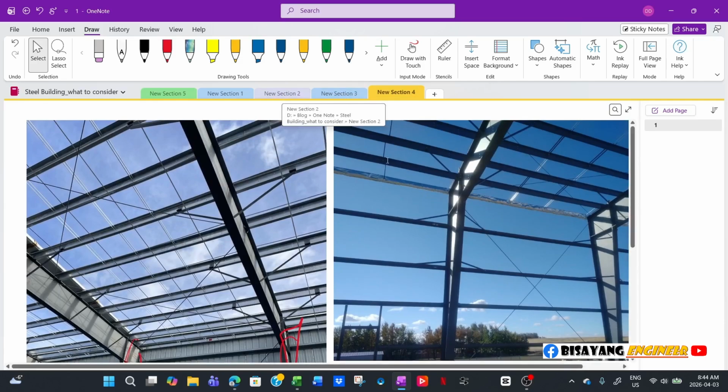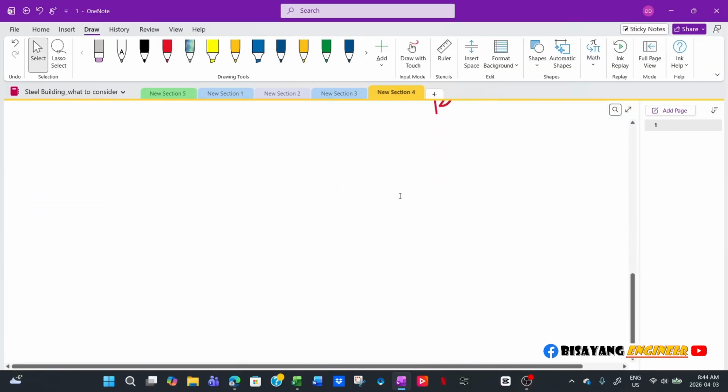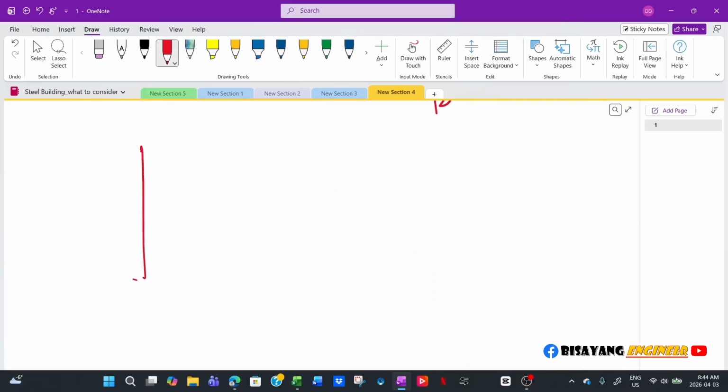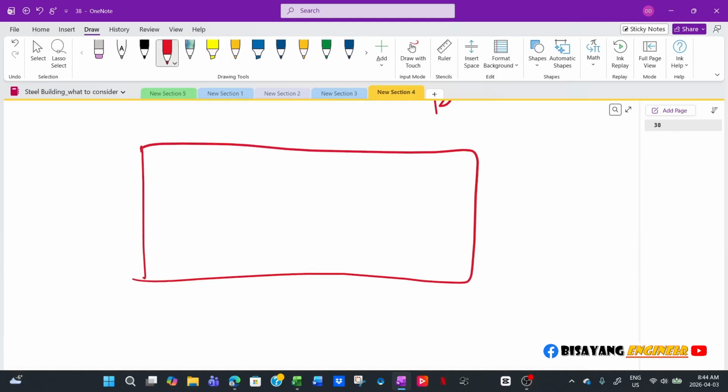But anyway, what a portal frame is, for example, if this is your building, and you have lots of overhead doors, because usually structures that use pre-engineered buildings are warehouses and shops, and you have tons of overhead doors. Now, since there is no room for cross bracing, because this is usually just sometimes 3 feet, sometimes 2 feet, you won't be having cross bracing here because that's an overhead door.